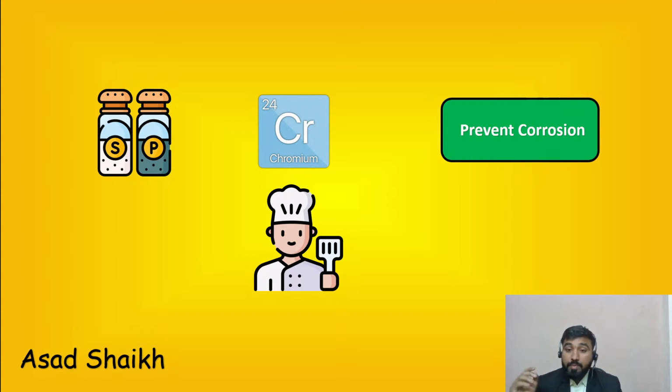However, be very cautious of the rating. It could be that your rating might be inferior, and for example, from a 300 flange rating, you might require it to be a 600 flange rating or 900 flange rating, depending on that. However, fluid wise, you are good to go.